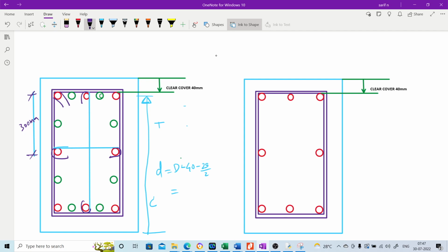The h that is going to be used in the equation will be the center to center between these two parallel legs of the stirrups. Okay, the largest of these. That means this is also h. For example, this distance is also h. However, we have to take the largest of the h values. Okay, so we will try to see how that has to be found out.